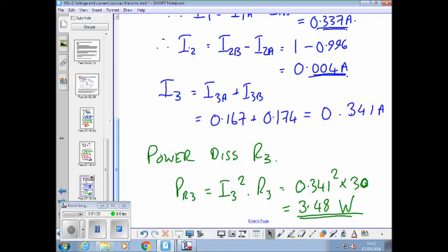The other two we're going to look at in detail, Norton's and Thevenin's, are good for a different purpose to this one. Norton's and Thevenin's is where you're interested in the current and voltage situation for one component in the circuit, the load resistor. This particular method will give you all the currents in the network.